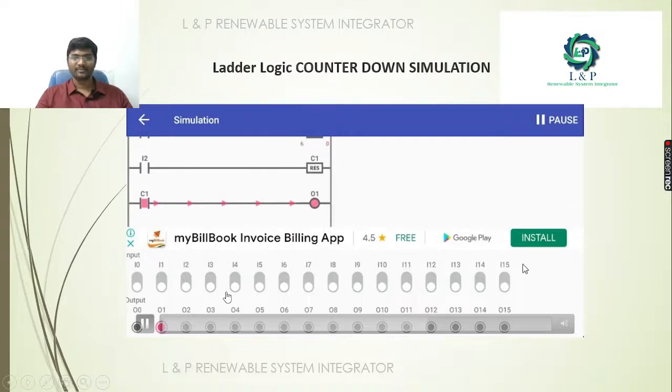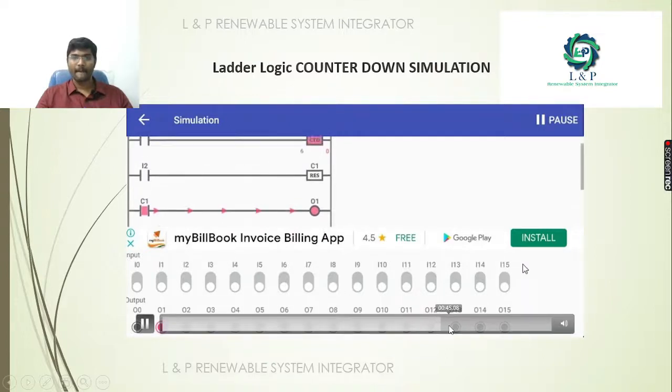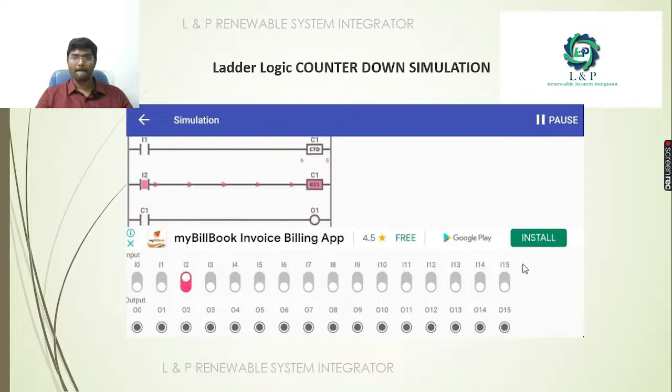Okay. Now what we are going to do is reset the memory of this counter. So we are enabling the counter, and when we press the reset push button using input I2, the count is getting reset. Input I1 is the enable. This is how we can use the same countdown operation. This is how the countdown timer will work: 6, 5, 4, 3, 2, 1. Simulate.